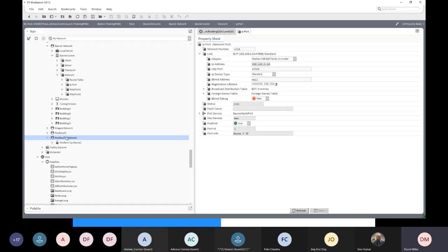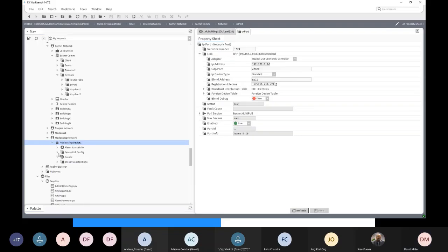So you can set up an FX server to have Modbus IP devices coming into the server directly. You do have to have a device license for each Modbus device you connect to, and the point count matters. The points that you map out are all included in the count. So yeah, you can go directly into the server.